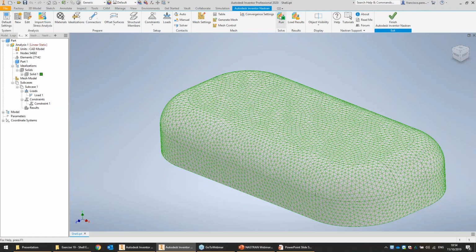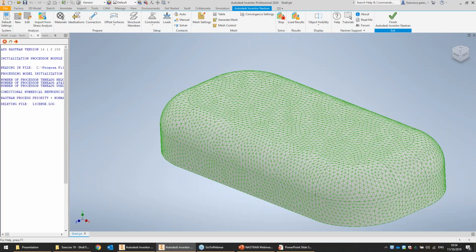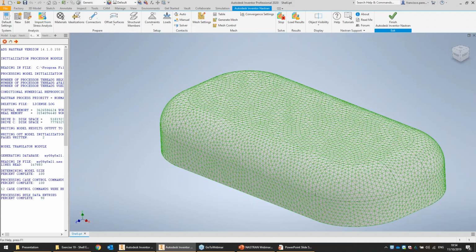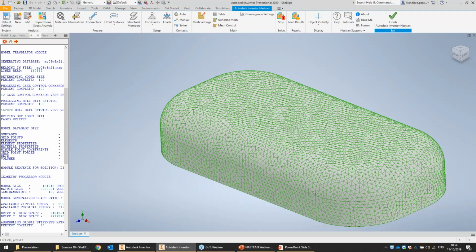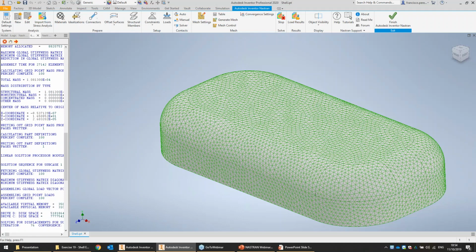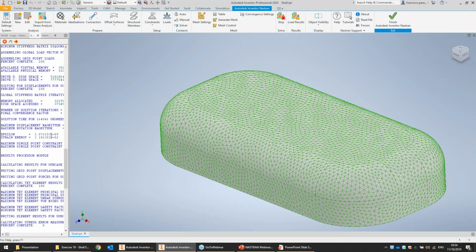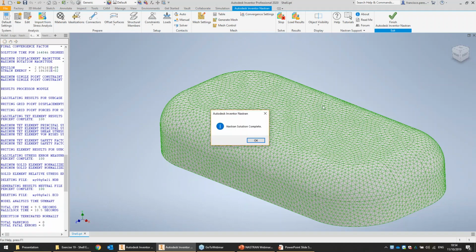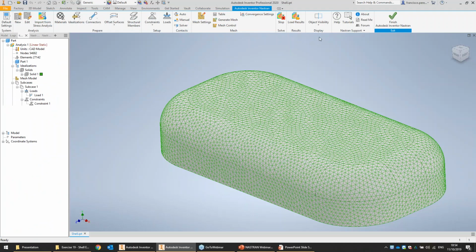And here we'll do a very, very quick linear static study using a solid idealization. So basically it's just a solid as per business as usual. So we're just going to quickly note down what stress is induced in it. And we're going to rerun the study, but this time using shell elements. And shells are very, very quick to learn and very, very useful.